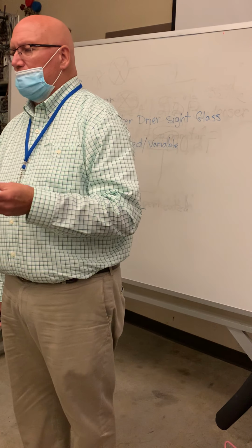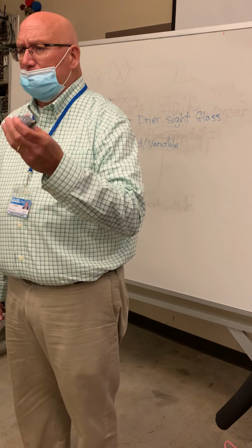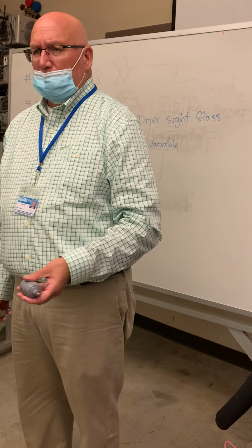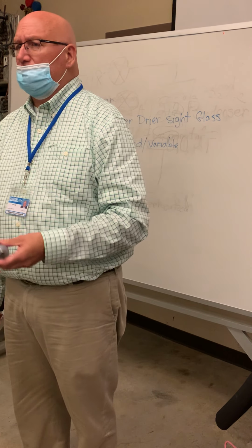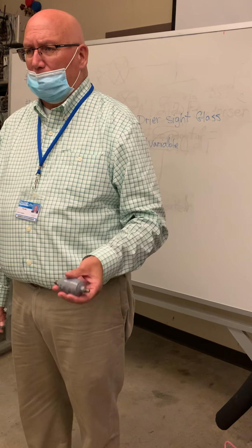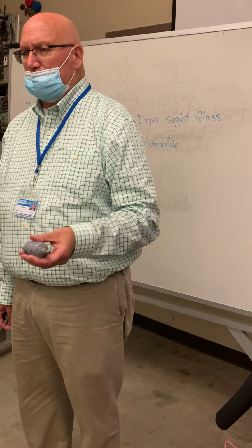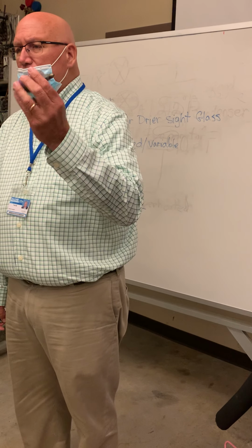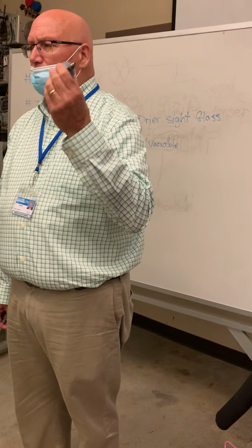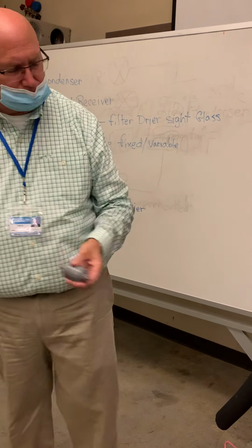That's why we use a device called a vacuum pump to reduce the pressure in a system to a point that water boils even if it's 40 degrees, even if it's 30 degrees. We want to boil that water out of it, get that water vapor out, because that is an enemy of the mechanical compression system. So this filter dryer has a desiccant quality that will allow it to absorb moisture that we maybe didn't get when it was vacuumed out.